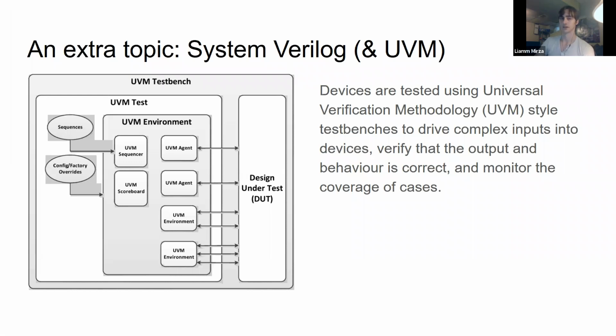Your sequences will be stuff that you write that determines what inputs will be driven in. The goal of these test benches is to drive the complex inputs to test the devices, verify that the output and behavior of the device under test is correct, and monitor the coverage of cases, to ensure that every single possibility within reason has been covered.